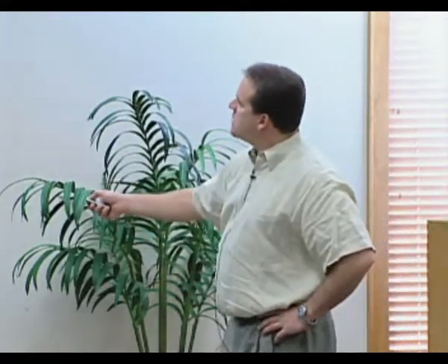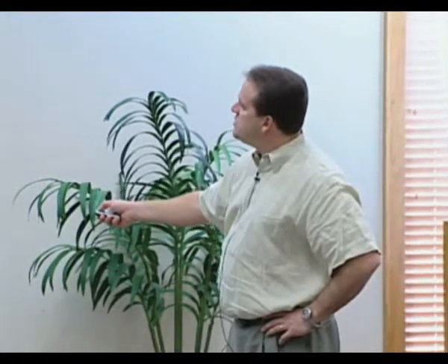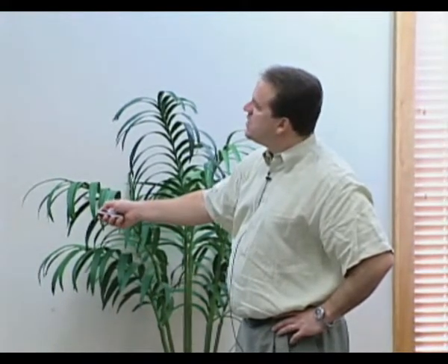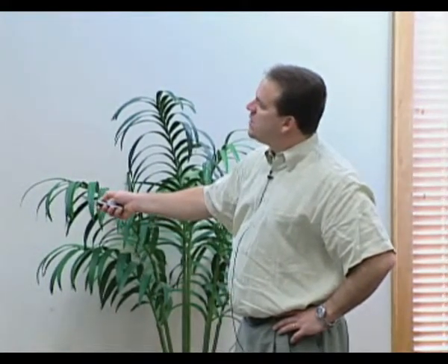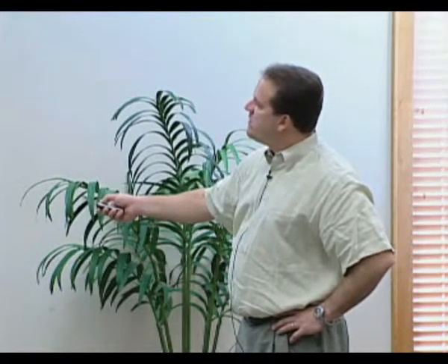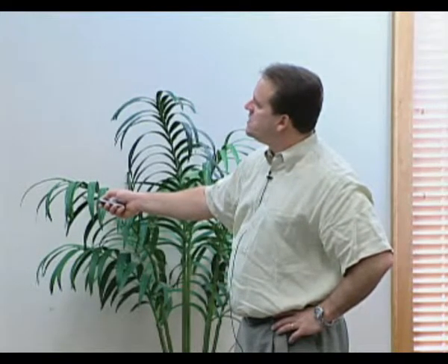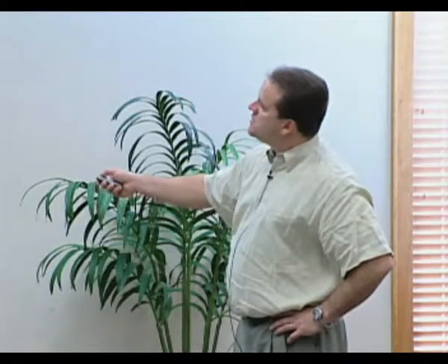So what we're doing is going out and taking that heat energy and dispersing it into the earth, and pulling back in that cooler energy, that 55-degree temperature basically, through this energy fluid and into our system to be distributed through the home. In the heating season, we reverse that. We're taking that cool air out, bringing it out into the earth, absorbing the heat energy from the earth and bringing that back into the system and converting that energy into heat for the home.